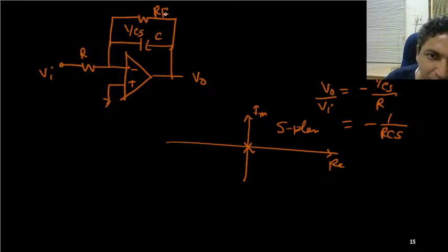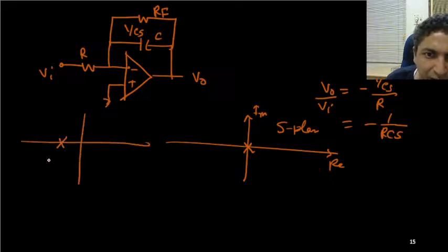It will be absolutely stable and you will see that your pole will be on the left hand side, but very close to the imaginary axis. Then it can behave as an integrator. If this pole is very close to the imaginary axis but on the left hand side, it will work as an integrator, but it will be more stable.